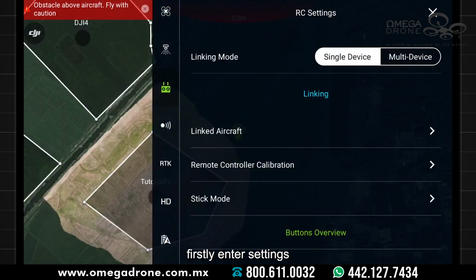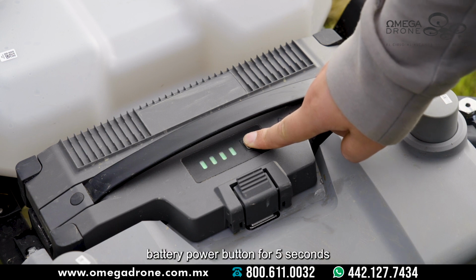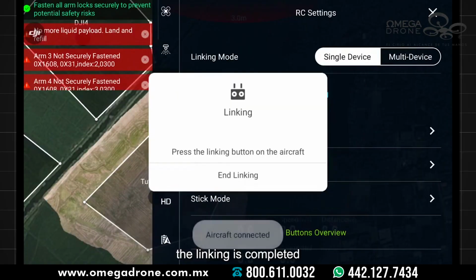Firstly, enter Settings. Enter the remote controller interface. Click Link. Then the remote controller will prompt a DJI voice. When the drone is powered on, press and hold the battery power button for 5 seconds. The battery power indicator will flash alternately. When the remote controller beeps twice, the linking is completed.